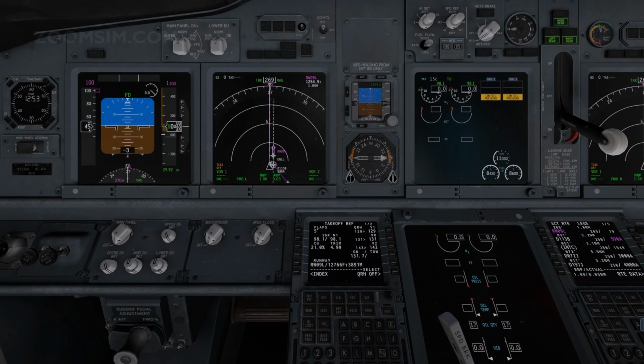In the reset position, pointer and shading are removed, fuel used is reset to 0, and fuel used is displayed momentarily, decreases to 0, then displays fuel flow. Move switch to reset, then rate. Engine instruments, check. Verify that the primary and secondary engine indications show existing conditions. Verify that no exceedance is shown.